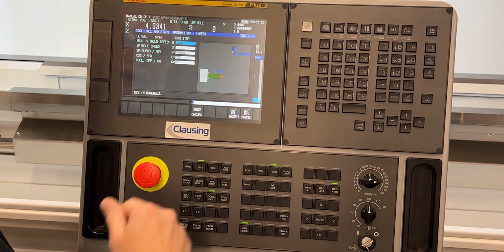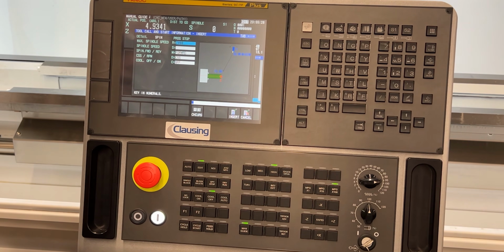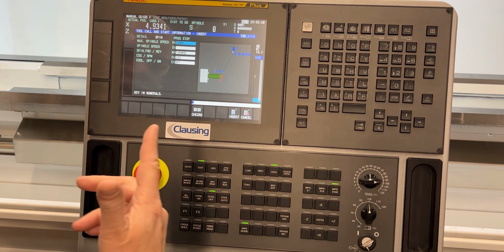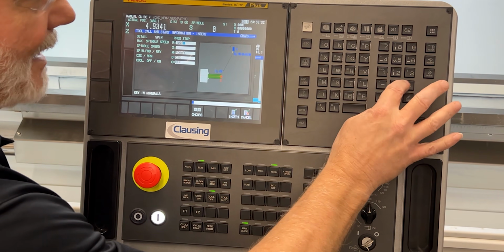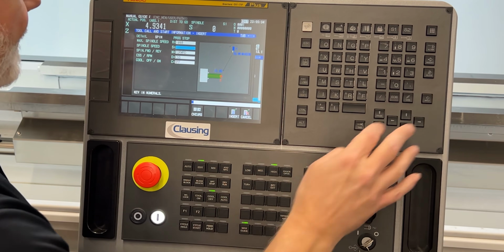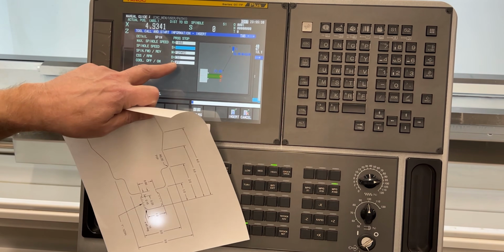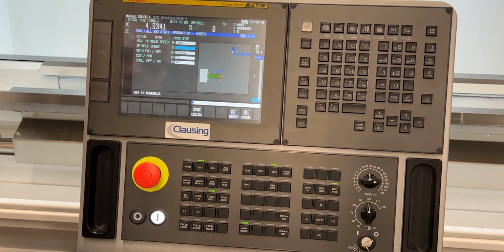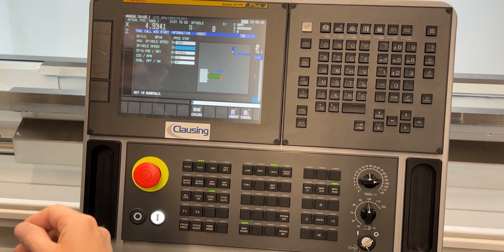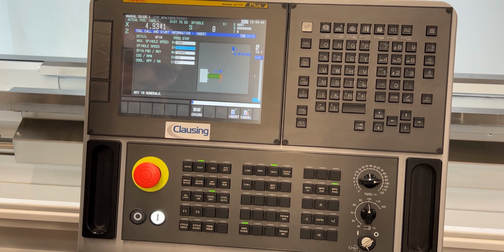And then my spindle speed is our max spindle speed. We can still put in there 1,000. We may not run it that much or that fast, but because we're going to change CSS to RPM when we get down there. So spindle speed, we have to base it off of RPM.